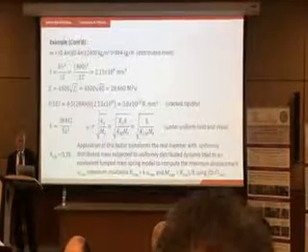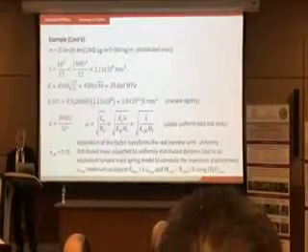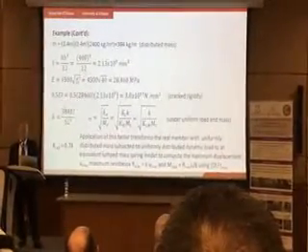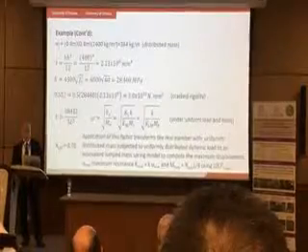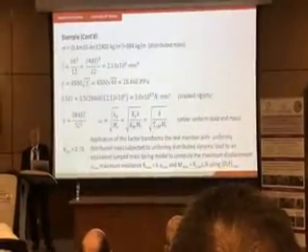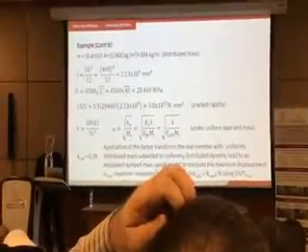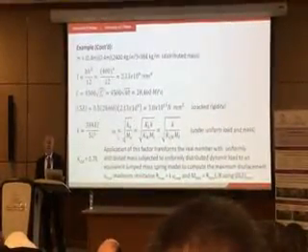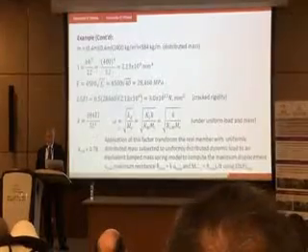So I have cracked rigidity. Stiffness is a stiffness coefficient; it's in every structural analysis book. So I know stiffness, I know mass, I know the load mass factor to convert distributed mass to lumped mass. Now I can find omega, and omega is frequency.